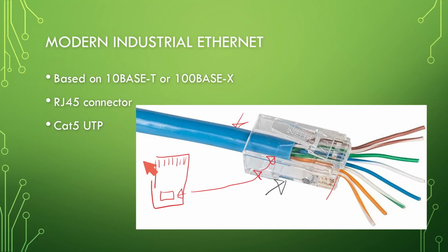The other portion that you were crimping was actually every one of these little metal connectors. If you look at a front view of these things, some of them are 2 or 3, but it kind of looks something like that. And when you crimp it, you put your wire right here, and it pushes all these little pins down into that copper wire. I think it's supposed to be 3 if you're doing a stranded wire, and it's 2 if you're doing a solid wire. But yeah, so that crimping tool is actually crimping 9 different things, 8 pins and that little piece of plastic.